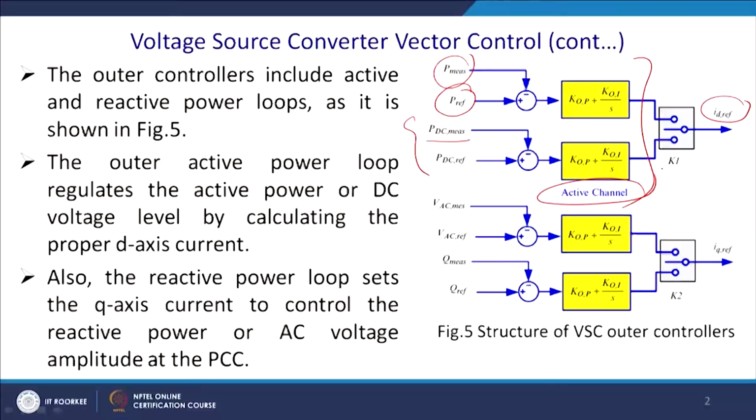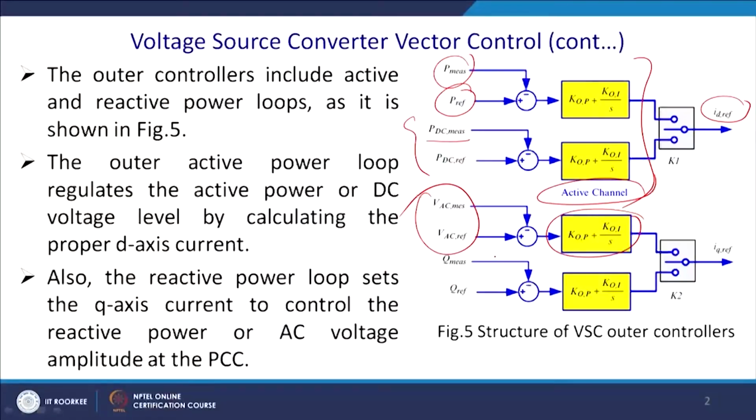Generally in islanding mode you go for DC power control, and in grid connected mode you go for grid power control. Thereafter you may have a sag or swell, but you require to maintain the voltage at the rectified DC output. When you have a sag, your DC link voltage will come down and you require to pump up the DC link voltage. Then this PI controller comes in, and ultimately that will be boosted by taking the extra reactive power.